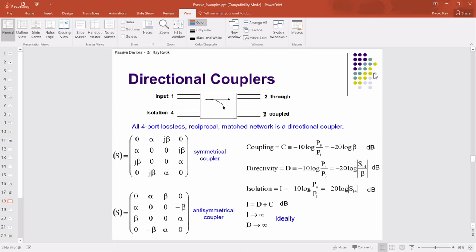So just to make sure, how do I know I'm sending power through my antenna? Well, I can put a coupler there. If I detect the power go through this line, then I know, yes, I have power going to an antenna, right? Or how do I know I'm receiving power? Same thing. So if you put 2 couplers here, you can detect whether you have power coming in or power going out, depending on how you oriented your coupler.